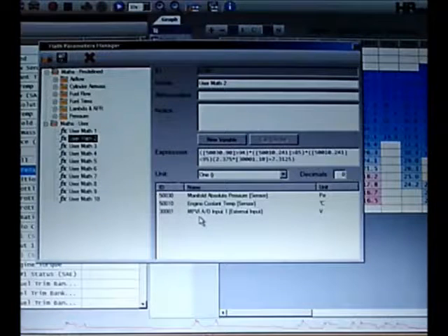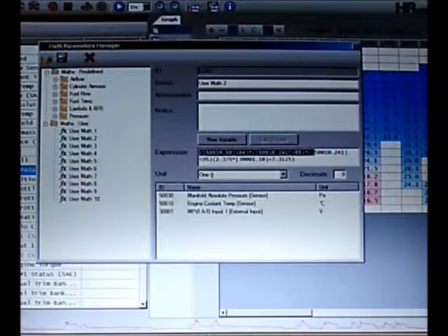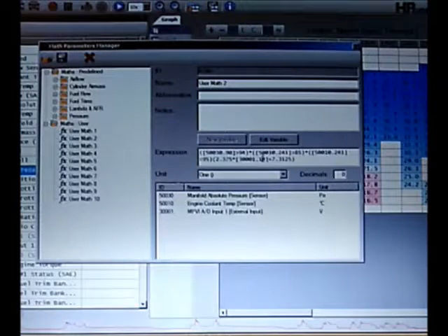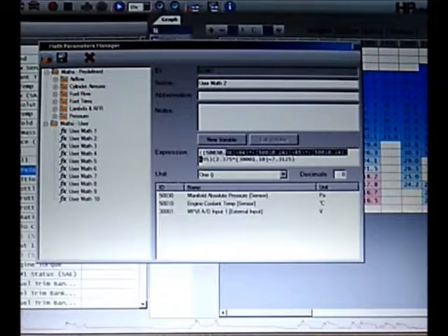okay, so what I did here was basically I'm still recording the air-fuel ratio, no different than before, and no different than the wideband O2 table. I'm still recording AFR values to put in these cells. The only difference is I applied some filtering in the actual equation. I didn't filter it on the main screen like I probably should have. Instead, I just incorporated it into the math formula here, which I didn't really need to do, but I did anyway. And also, I needed this function. I needed a math function regardless because I'm still recording AFR, which means I need the transfer function, and here it is. The only additional part is that I put these conditions here.